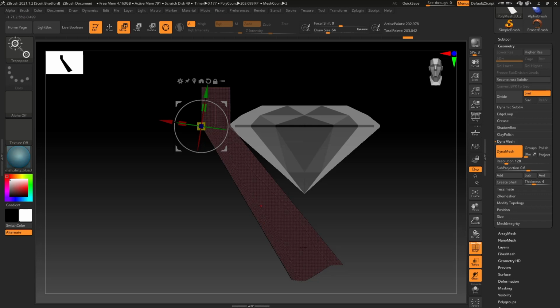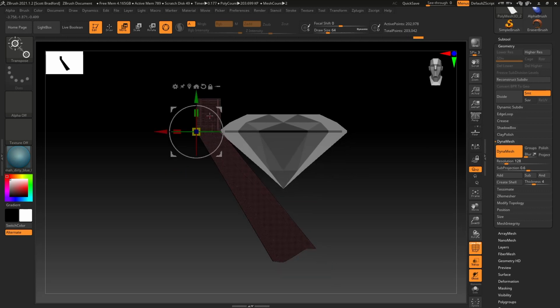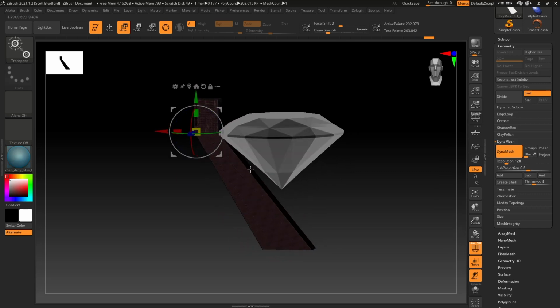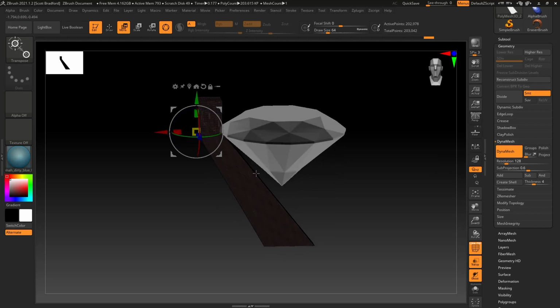So last thing we need to do is, because we rotated this, we kind of messed up our bottom angle here, so we're going to clean that up. Now I did rotate the gizmo when I was making this, so I need to reset the orientation. So hold Alt to unlock the gizmo and click Reset Orientation. And now I can hold Control to clip and do a scale in Y by dragging up. So something like that. That's pretty good. That's our prong right there.